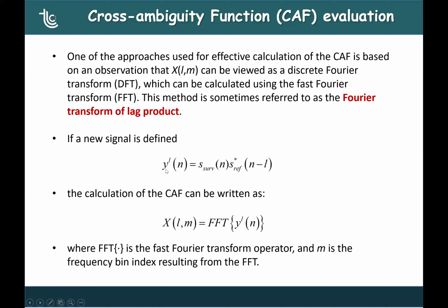Let me explain a little bit better. As you can see, this signal y depends on n, so it is a sequence of values, but it depends also on L. So we have multiple sequences, one for each value of L, so for each delay. And then we need to calculate the FFT of each of these sequences, okay? So for each value of L, we calculate the FFT.